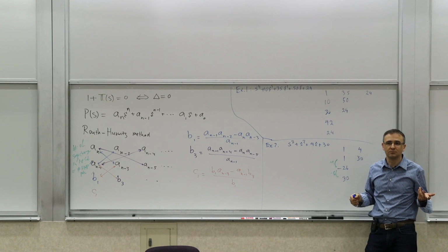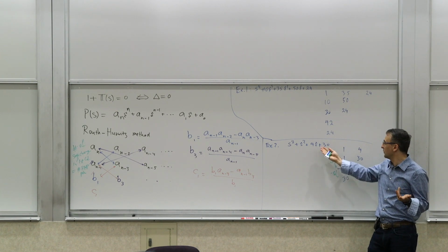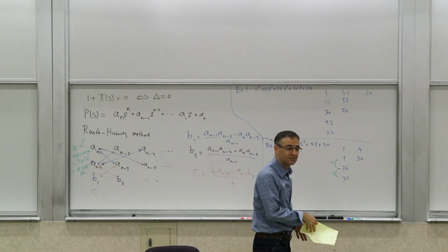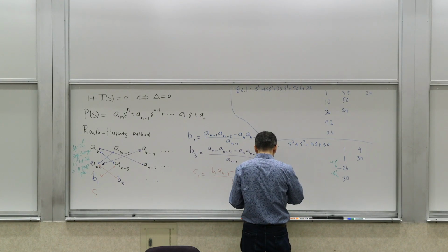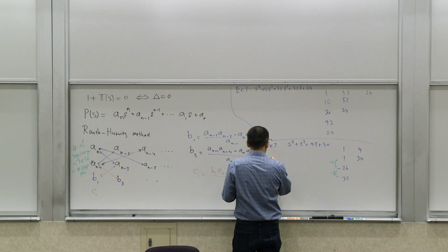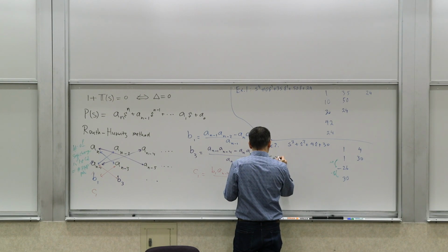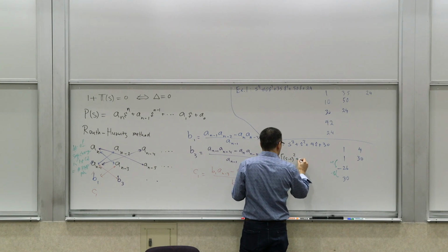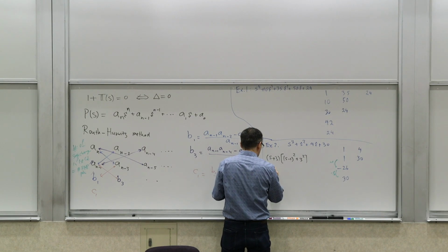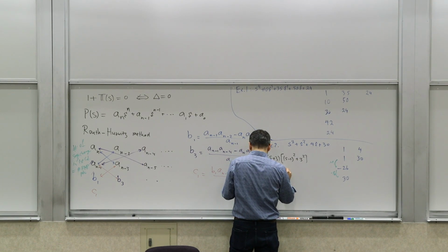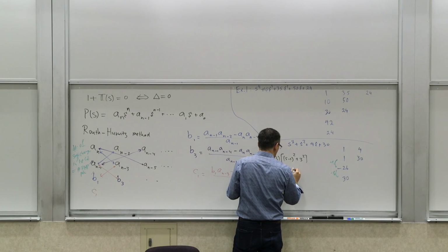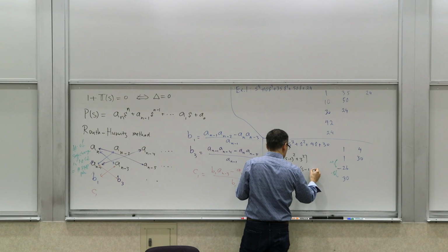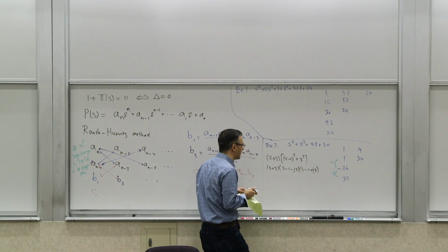Now, you look at something like this, it's not obvious just by looking at it that you have right half plane poles, right? Because all the coefficients are positive. But in fact I can tell you what the factorization of this thing actually is. This was constructed to have a certain factorization. It's s plus 3 times s minus 1 squared plus 3 squared, which you can write as s plus 3 times s minus 1 minus j3 times s minus 1 plus j3.